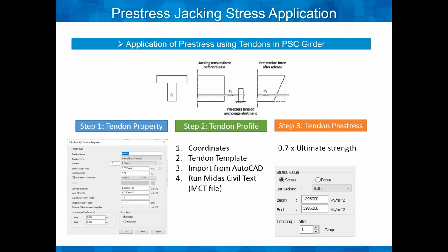So the jacking tension force is the force that is applied while we are applying the force on site itself. So it is without the losses. The losses will be automatically calculated by the program. The immediate and the long-term losses will be automatically calculated by the program.